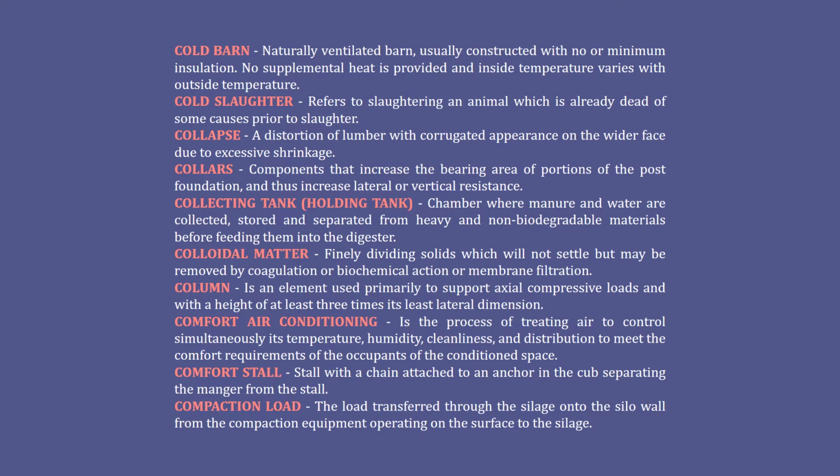Colloidal matter. Finely divided solids which will not settle but may be removed by coagulation, biochemical action, or membrane filtration. Column is an element used primarily to support axial compressive loads and with a height of at least 3 times its least lateral dimension. Comfort air conditioning is the process of treating air to control simultaneously its temperature, humidity, cleanliness, and distribution to meet the comfort requirements of the occupants of the conditioned space.